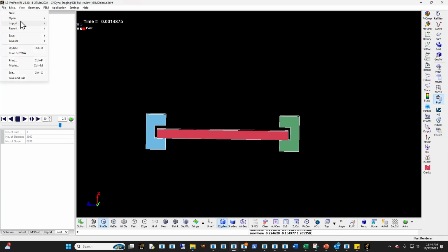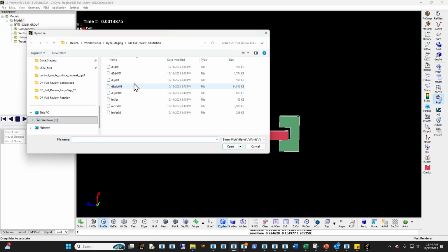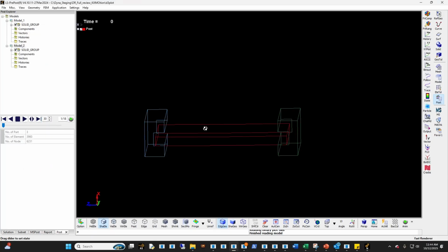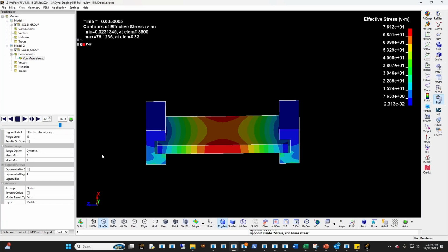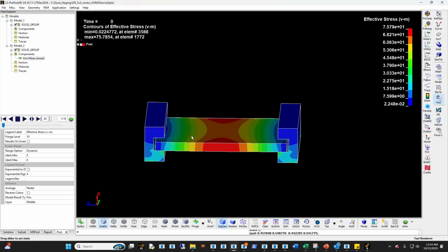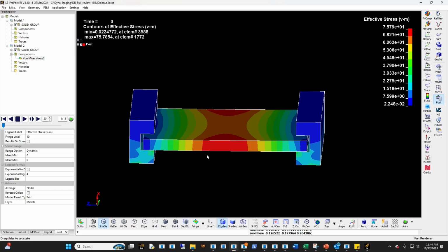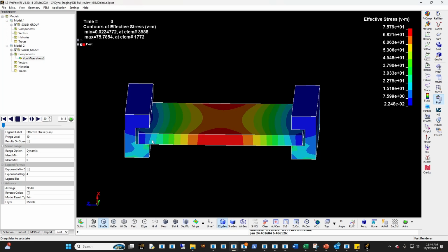Actually, I need to turn on the full transient analysis before I can probe. Sorry about that, that's what I forgot in my previous example. So in this case, you can see how at t equal to 0 the plate is not in full contact with the slot. Now, if I probe stress, you can see that ringing right there. That ringing still exists. But at t equal to 0, we could have killed that ringing by setting the scaling factor to a number way lower than that. In this case, we didn't. That's why you still see some ringing in the system.